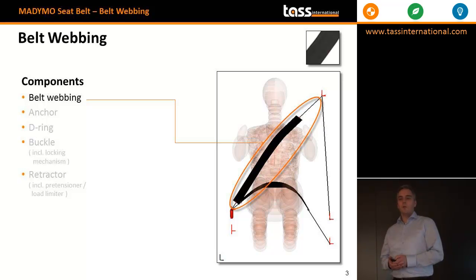Here you see an example of time-based triggering in MADYMO. An example, say for retractor spool locking, how can you model this in MADYMO? With time-based triggering, basically you predefine a certain time in your simulation at which the spool needs to be locked. So then you use the element switch.time, and with switch.time you can switch from false to true, and once that switch is used under belt retractor, then the belt retractor will make sure that the spool is locked and no more belt payout is given.